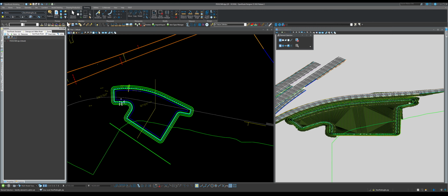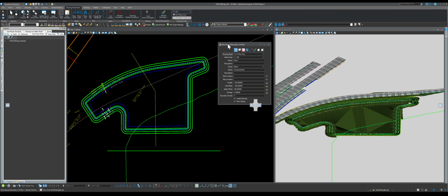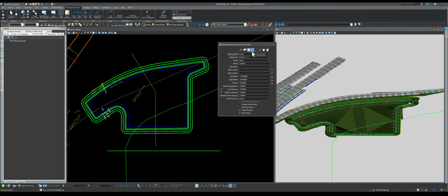And again, like I said, it depends on what the EOR wants, right? We can do 2, 3, whatever you want. For this example, I'm just going to do 1. Okay, then let's go to draw and production, and then let's go to name boundary. So this is the average tool to do cross sections, which, if I selected this, will do them like this per alignment, but that's not what we want. We want the cross sections to follow this line that I did non-plotting. So to do that, you need to go here to this cross section by 2 points.